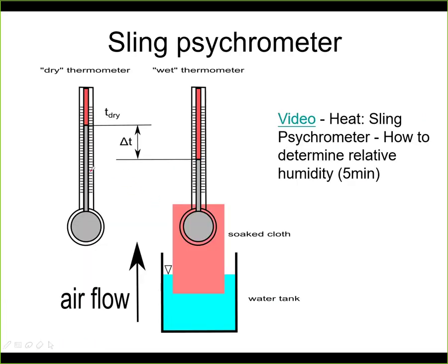You just need to take two temperature sensors and arrange them in this setup. The temperature sensors can be anything. So this could be a glass thermometer, for example, but it could also be some precision resistive temperature detector. So it could be an RTD, a PT100, for example. There are many available devices like this on the market.